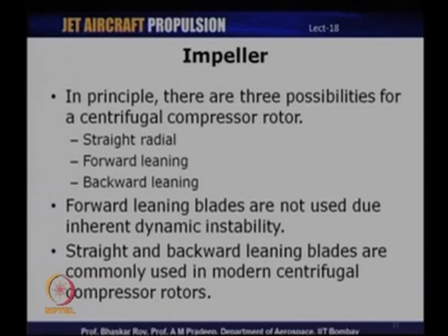So, what we will discuss next is about one of the components of a centrifugal compressor. When I showed you the schematic, you had seen that there are different components of a centrifugal compressor. We have an inlet duct, then there is an impeller, and one constituent of an impeller is the inducer, which I will discuss a little later. The impeller is the main section of a centrifugal compressor. It is the rotor of a centrifugal compressor.